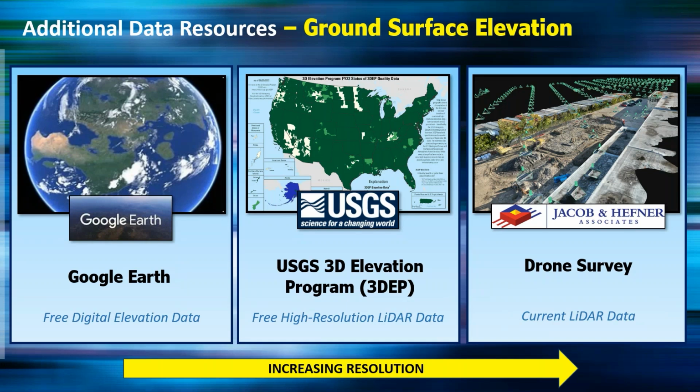And then, of course, if you need a survey at your site that's more up to date, you can do a drone survey. A lot of companies do it, but my previous employer, Jacob Hefner, does drone surveys, and they do a really good job. And that gets you basically current LiDAR data. And of course, moving from left to right again, you get increasing resolution, but it's also obviously increasing price for the drone survey.